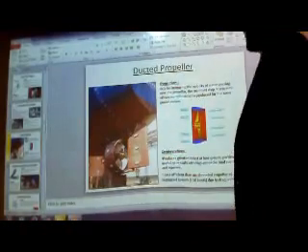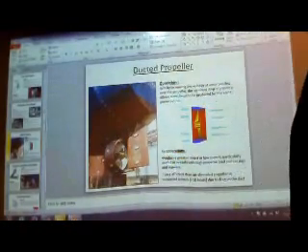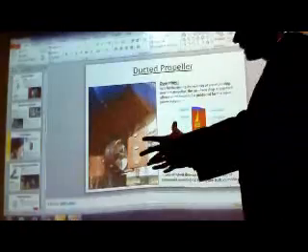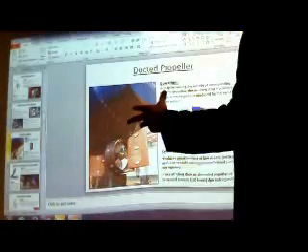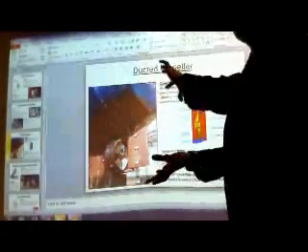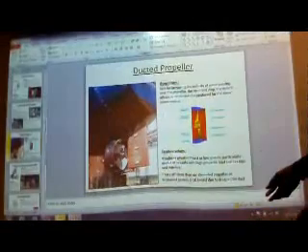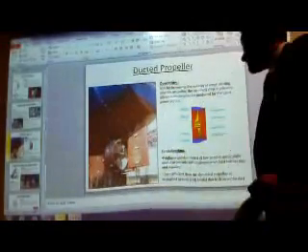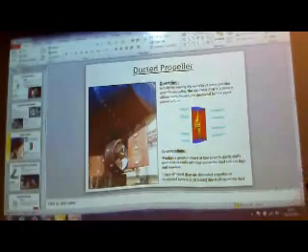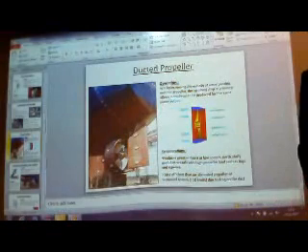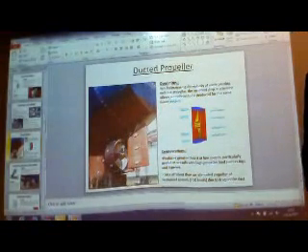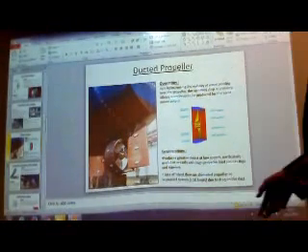Well, what is it? First of all, it is going to increase the efficiency of the propeller. You're going to make the flow more linear. You're going to duct it rather than losing it. So it produces greater thrust at lower speeds, particularly useful on vessels with high propeller load such as tugs and trawlers. Again, it's going to be on smaller ships where you need higher maneuverability.